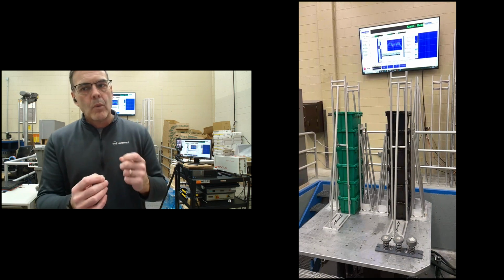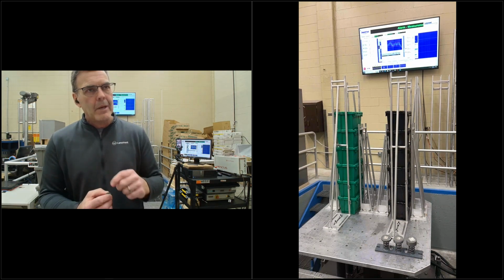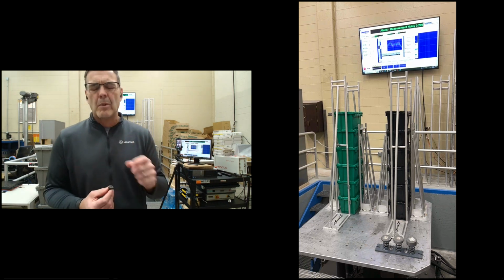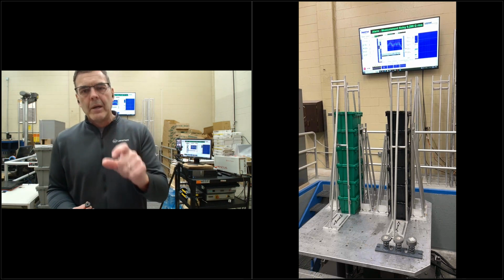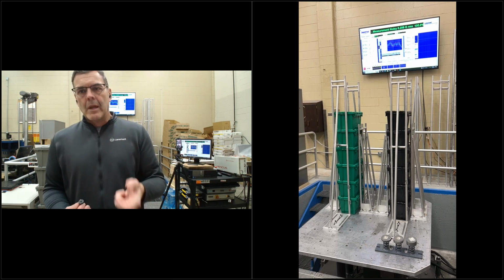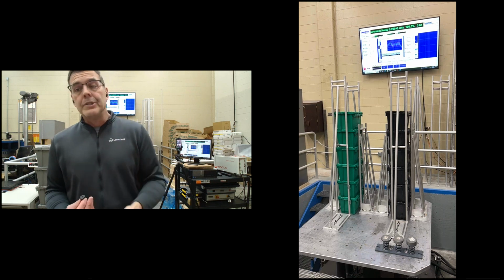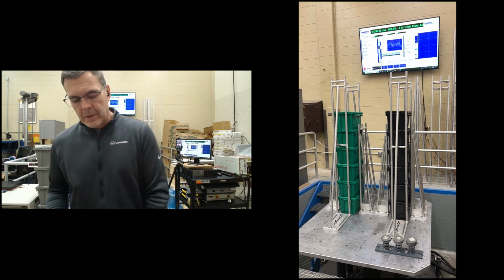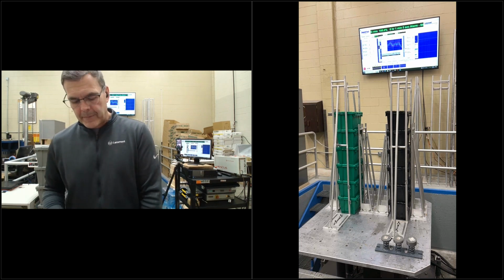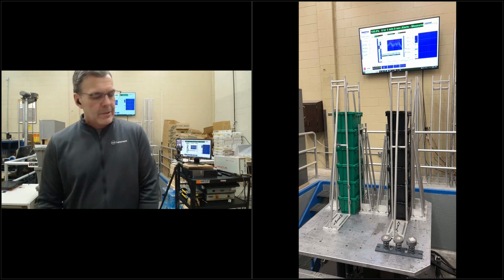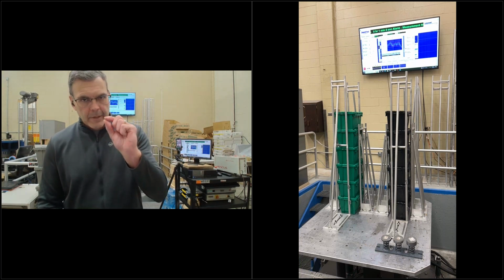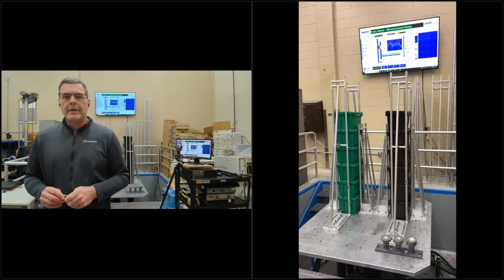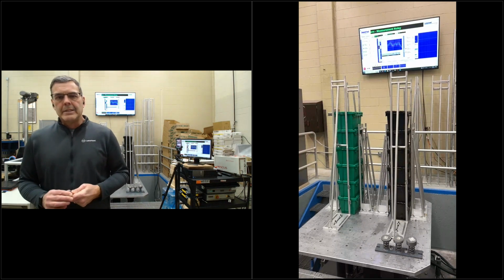And even hot melt works, as long as you're careful with hot melt sometimes, because of the temperature sensitivity of the sensors. They're usually pretty robust, but you don't want a big glob of hot melt, once again, acting like a cushion in some way to the attachment. So if you use it, you usually try to use a minimum of it, and you push down very rigidly, so you make sure that the layer of adhesive is small enough and stiff enough that it's not changing your measurement. So yeah, adhesive is the best.